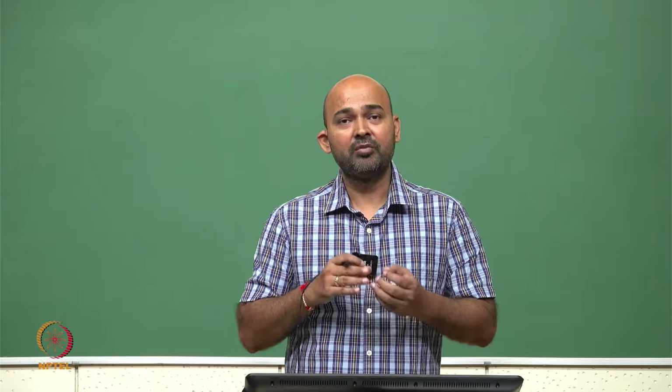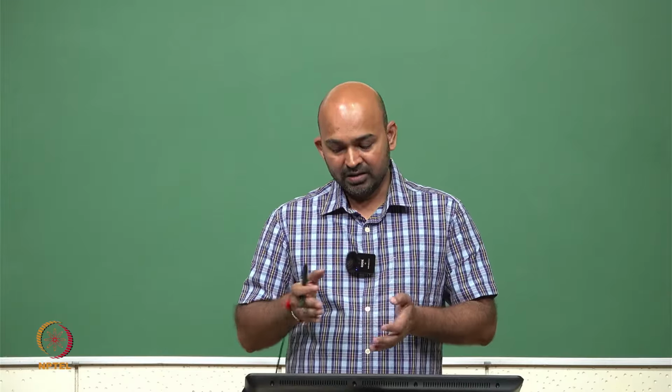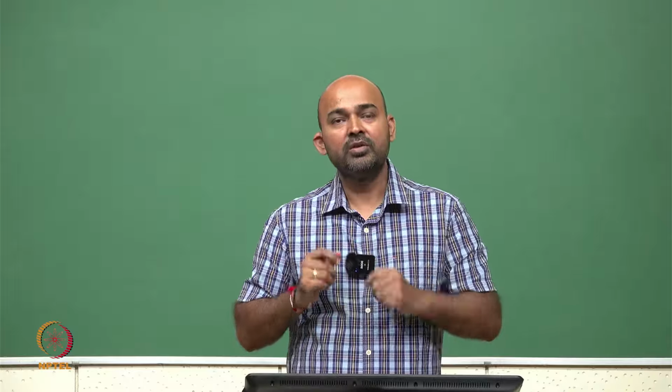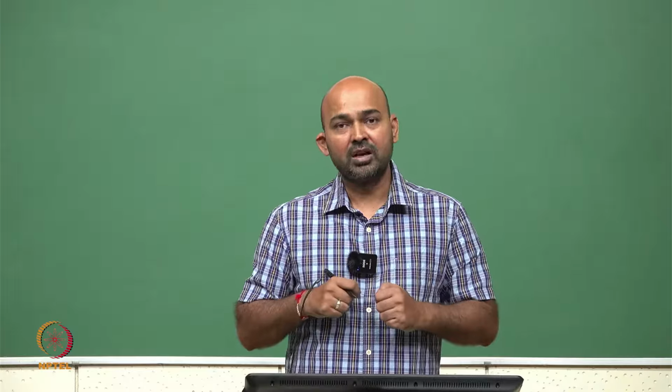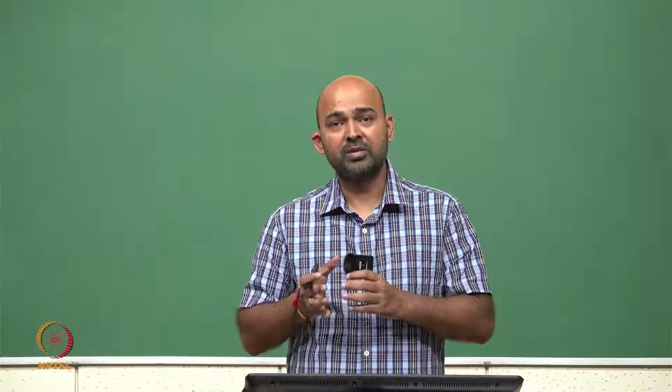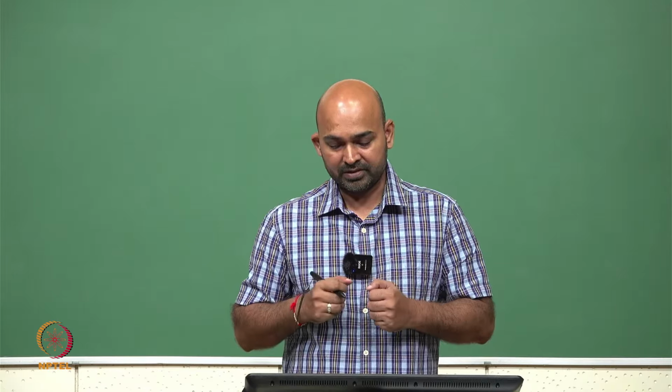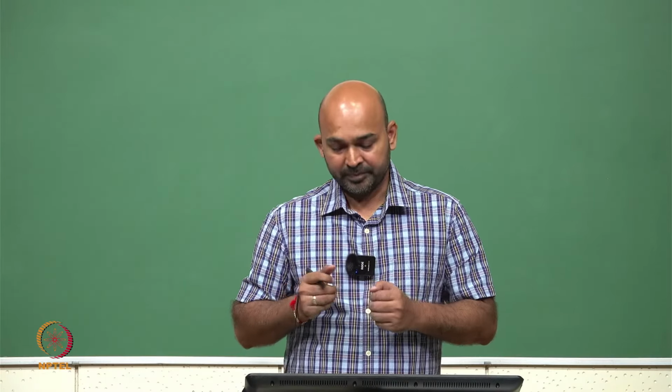So we have a trade off between the speed and the actual logic value of the output, which is the ground voltage R1 divided by R1 plus R2 into VDD. So, we have to decide at what point we want to have this R2 resistance fixed, because this is going to dictate our logic levels.